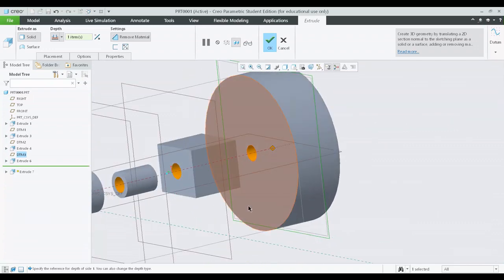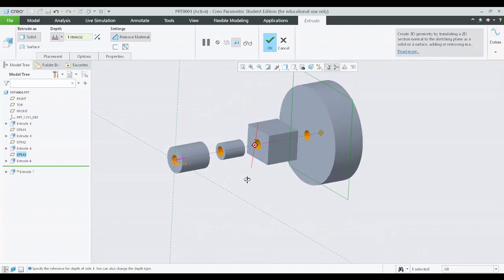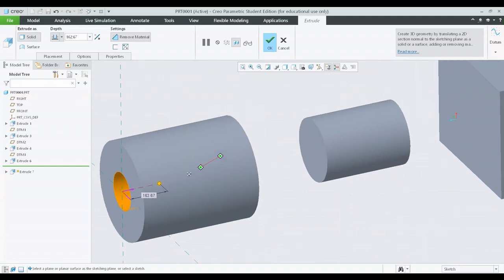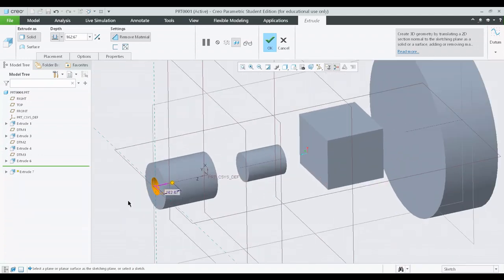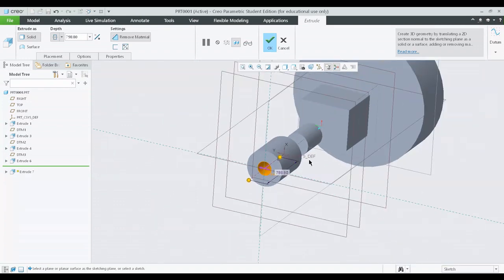So this is about more of the features of the material removal process. Generally we will use the first or the second option most commonly in all the geometries, because it is rarely required to create an intersecting hole continuously. And just remember one thing: the symmetric option is for extrusion on both sides. On this side we don't have any material, which is why we are not finding anything over here, but the material is getting removed on one side.